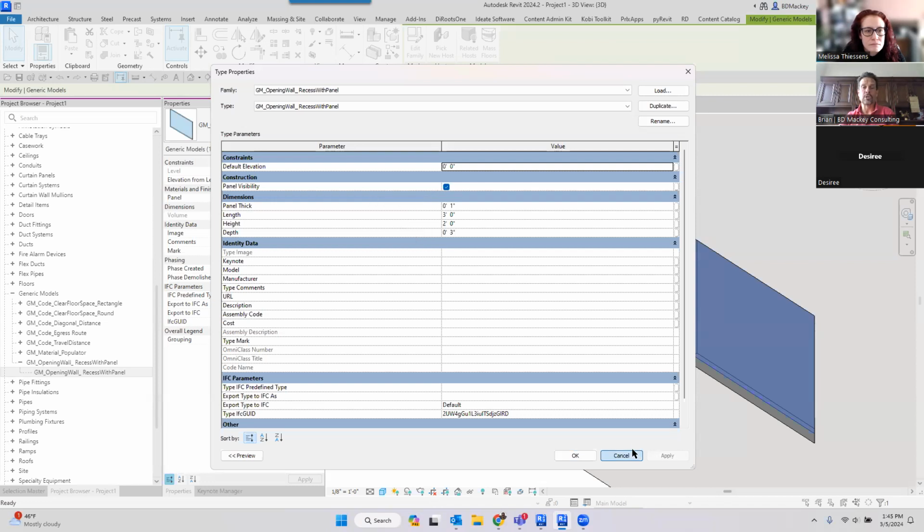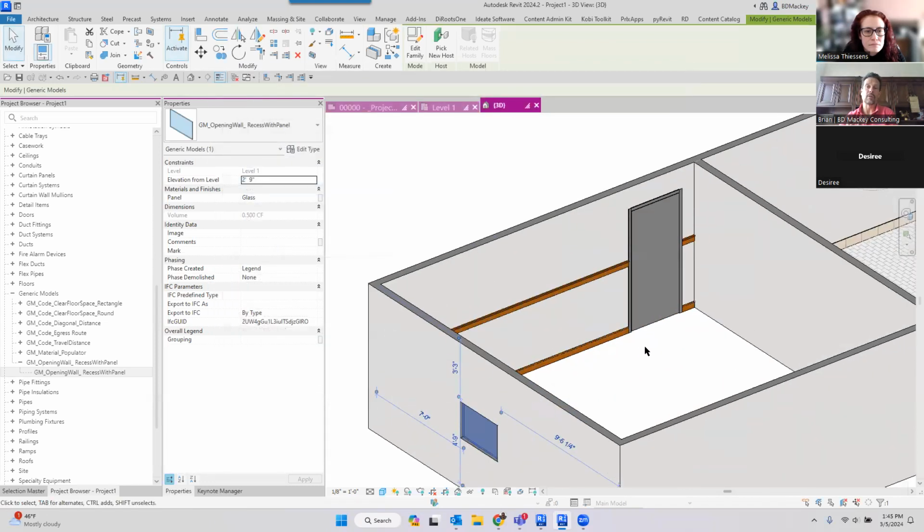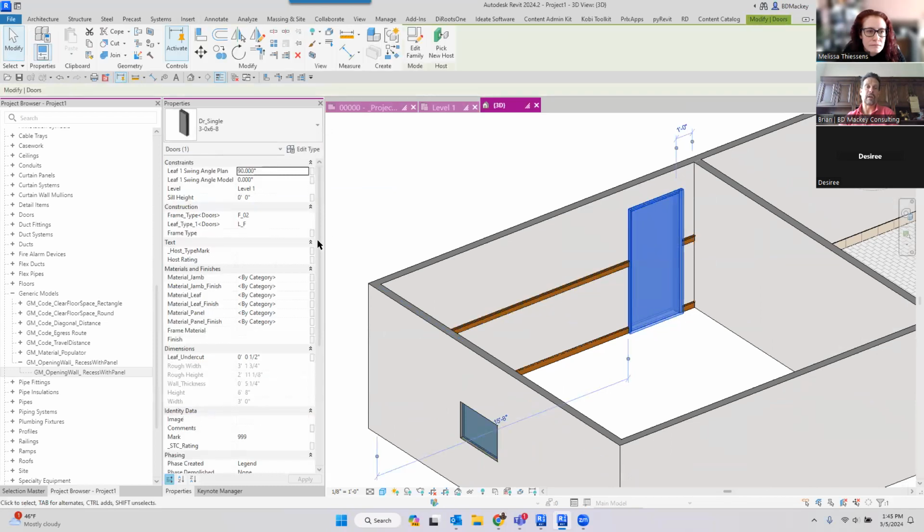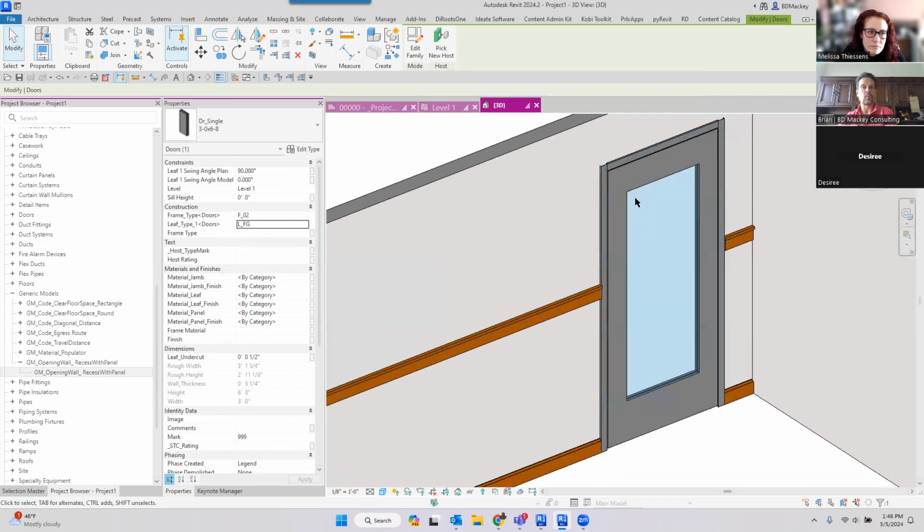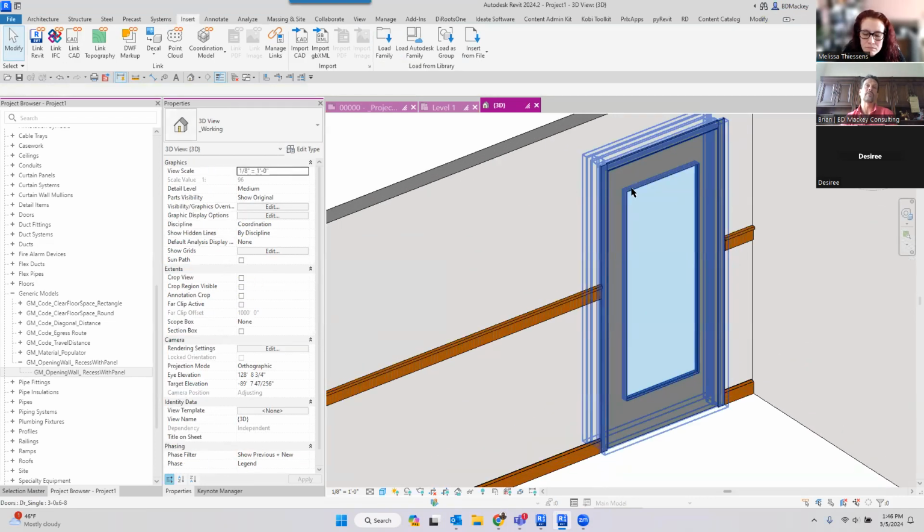Now, as for changing the type of that angled family, it's not going to be different than any other family. You're going to have to create a family type parameter. In this case, this is the one for doors, right? If I wanted to change this out from flush to a glazing, it's going to be the same thing. So you could put that family inside of there, make it work with a family type parameter, so you could swap out the angles. There's no way to make sure that those angles, if you change it from a 3x3 to a 12x12, adjust anything in the openings, unfortunately.